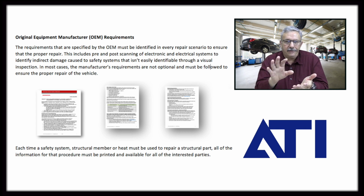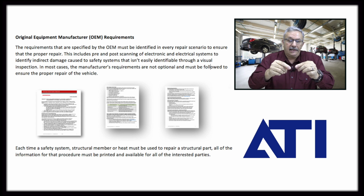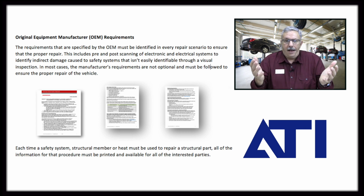It'll give us a couple different things here. First, it tells us things as simple as, did we have a connector that moved out and didn't go back into place? Because remember, I got parts moving all over the place, wire looms are being stretched to their max. In the middle, I may have a connector. Did the connector maybe come out and now I've got a drop in that, and now I've got an open circuit? I'm not going to know that unless I do a scan.